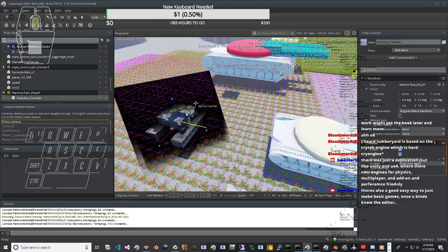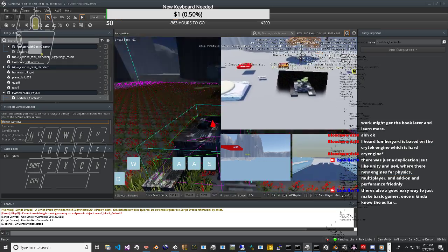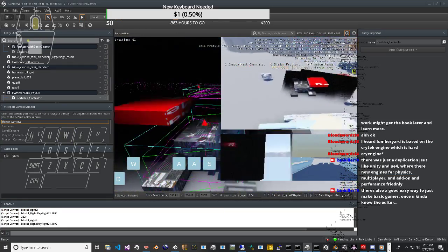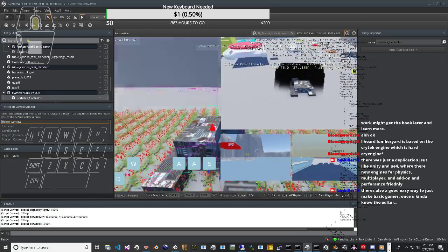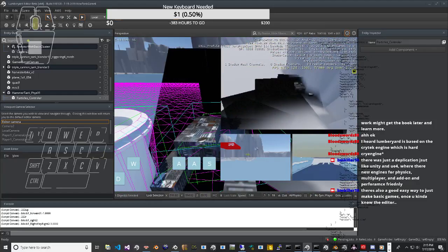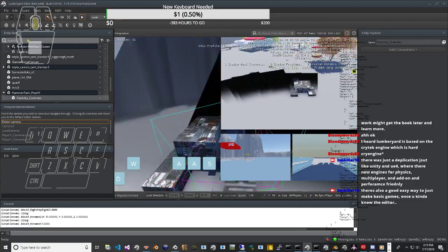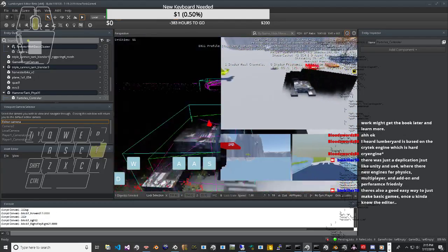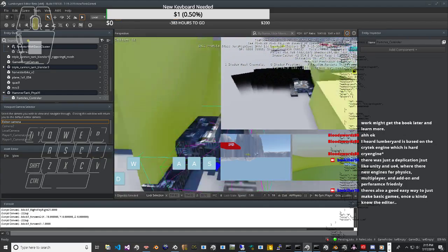A typical streetable sports car might weigh in at about 3,000 pounds, which is about 3,000/2.2 equals 1,500 times 0.9 equals 1,350 kilograms, which is about 1,350 times 9.8 equals 13,200 newtons, or 13.2 kilonewtons. Look, Ma, no calculator. Let's assume each tire gets a quarter of it, or 3.3 kilonewtons.